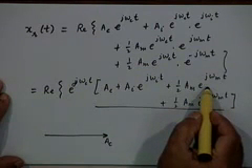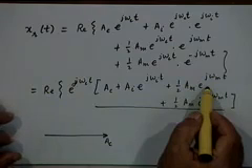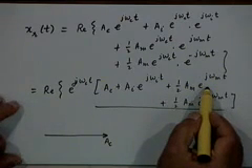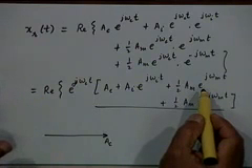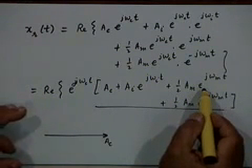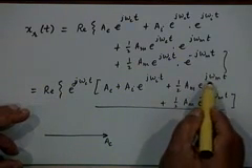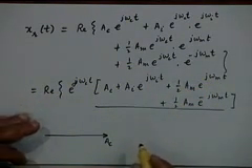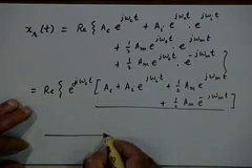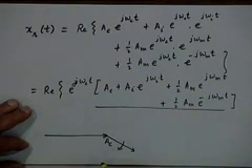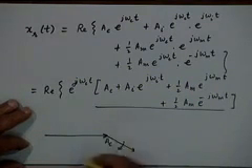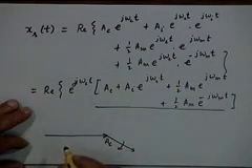This is rotating faster than the carrier phasor. So with respect to the carrier phasor, it is rotating at the speed of omega_m radians per second, let's say in a counterclockwise direction. So plus omega_m, let's say, means rotating in a counterclockwise direction, rotating like this, going round and round around the carrier.